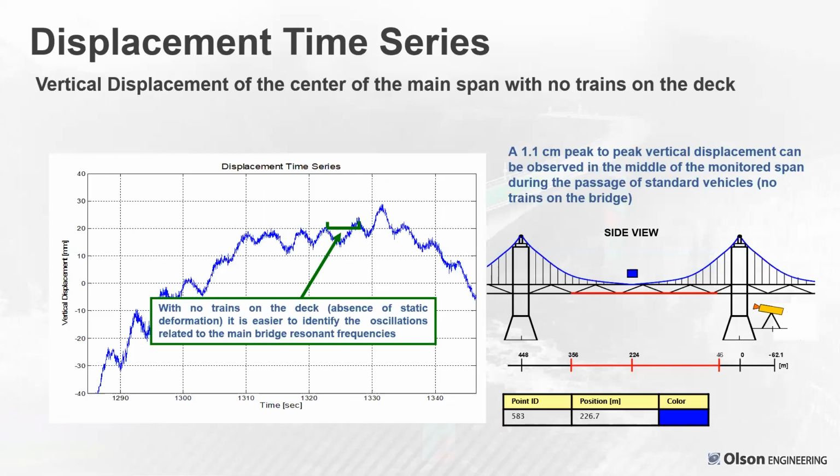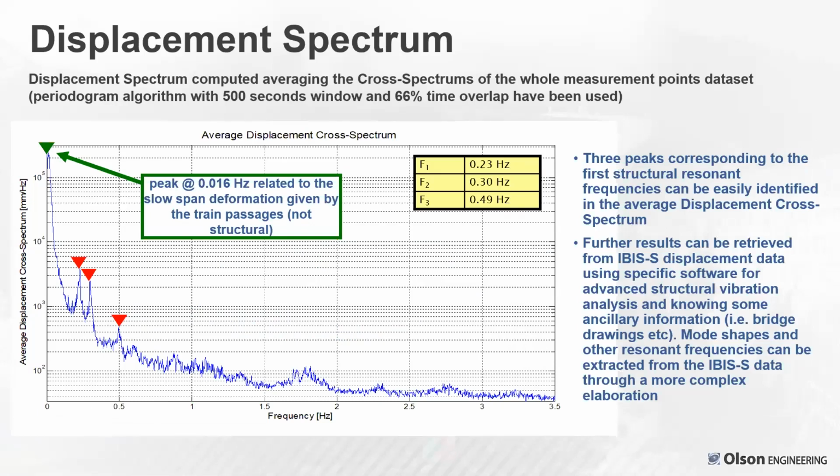So this just shows much lower displacements, less than plus or minus 40 millimeters, and just some drift and things moving during this time. But that's not very much displacement. So when you do the fast Fourier transform to look at the FFTs, if you will, or frequency content, there were three main resonances that showed up even in that data.